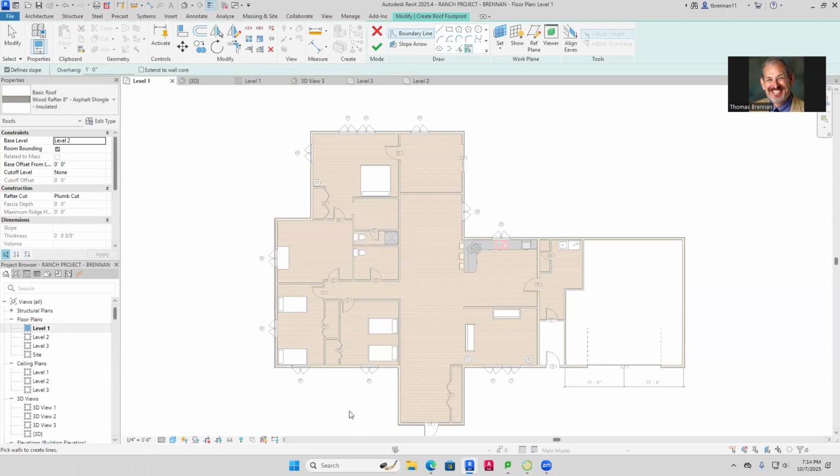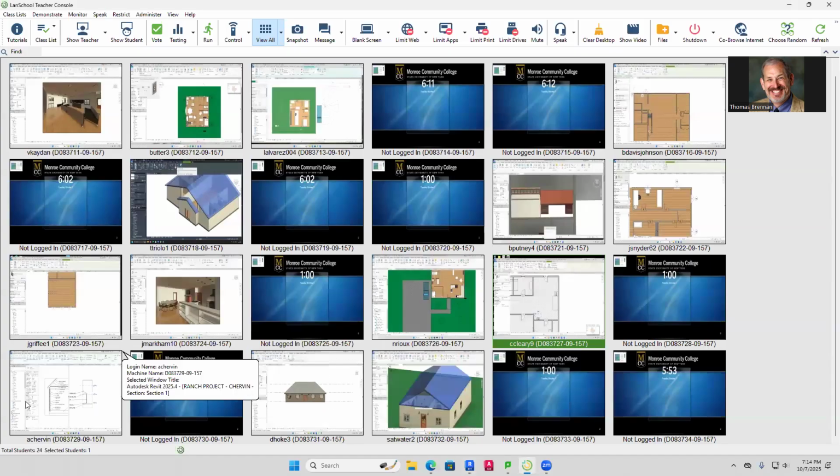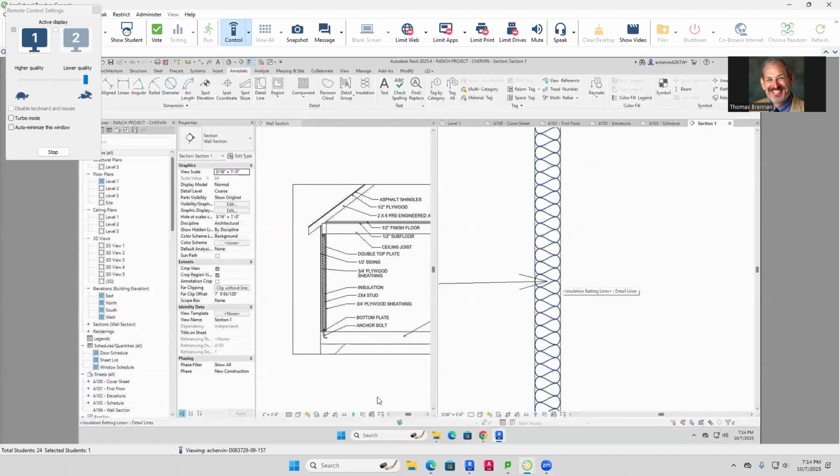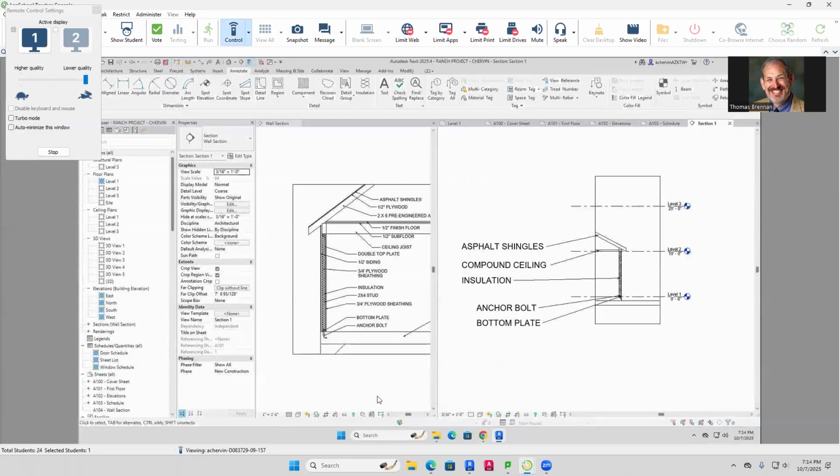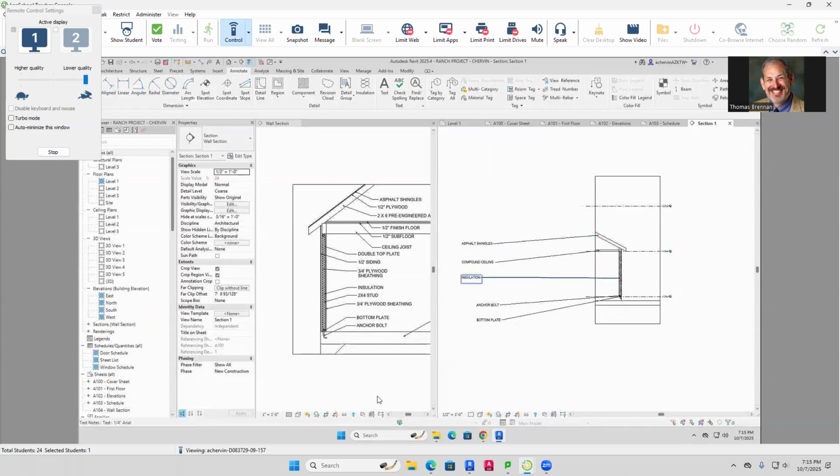You check if my section has enough fields, because there is not enough section in the wall, so I could point to anything. Okay, that's sufficient. I just want you to know how to do this. Also, change the scale to ½ inch equals a foot in that view. Down at the bottom left, change it to ½ inch equals a foot. There, right there. Okay, good.